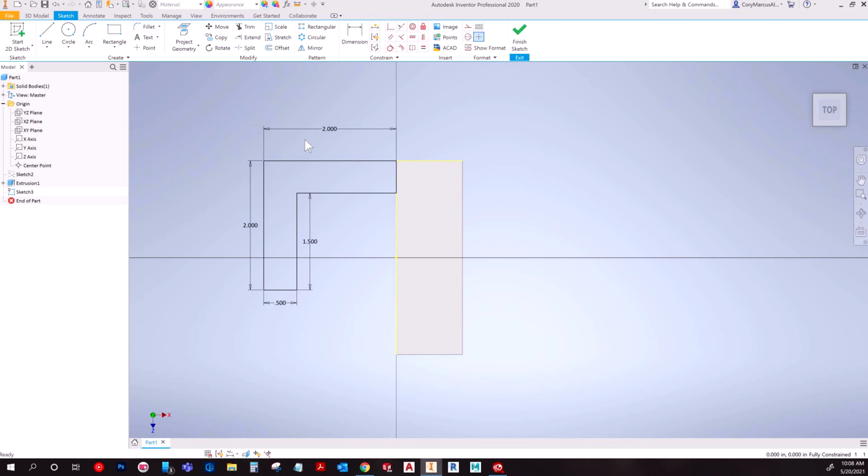I can't tell you how many times I've seen people draw and they've got a constraint in there that they don't realize Inventor inferred, and it can make life insanely difficult. A lot of times it happens with angled dimensions because you're supposed to draw things in Inventor similar in scale to what you want it to be, and then you adjust the relationship accordingly.